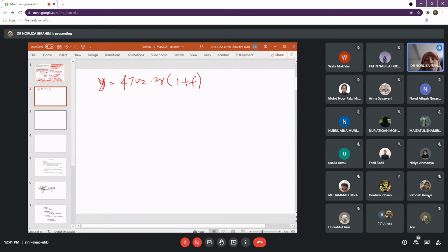Now for oxygen, coming out of the reactor, which is your X, okay, what can you do? The simplest way is you solve atomic balance. So I show you O balance. You solve atomic balance. Yes? O balance, O in your inlet will be from the oxygen in the air.